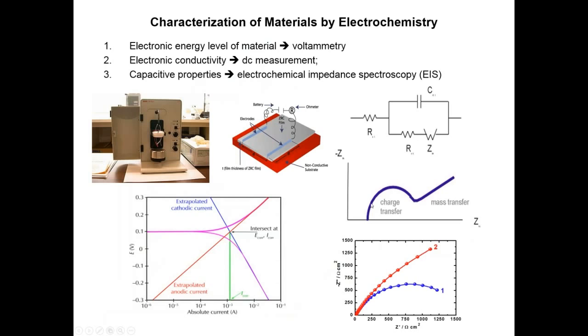On the other hand, capacitive impedance measurements enable us, for example, to use a Bode plot or a Nyquist plot to predict the transport of ions, and then that transport or that barrier of transport can be broken down or modeled into an electrical circuit diagram as shown here, where we can include the capacitance, the resistance, and the impedance as part of the model circuit. And from here on, we can characterize the corrosivity or the transport of ions in and out of a coating or an analysis of an oxidized metal.